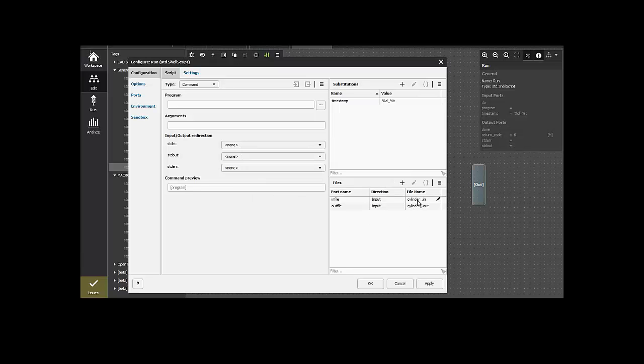Cylinder is just the name of the Amesim project. So the command is pilot. It's a batch adapter for Amesim running in batch mode, and the argument will be just the project name.